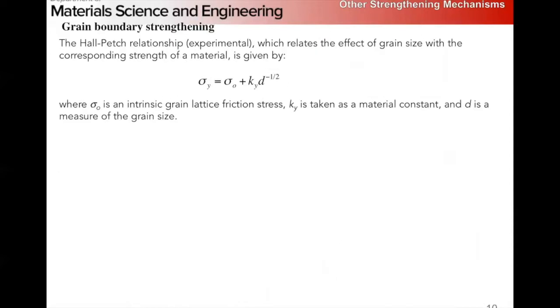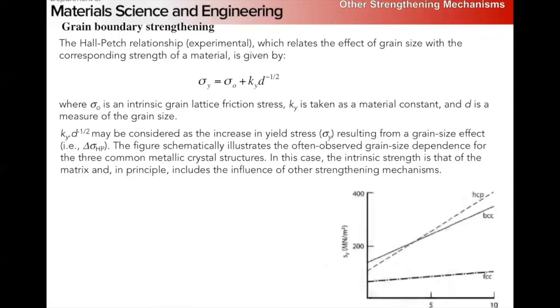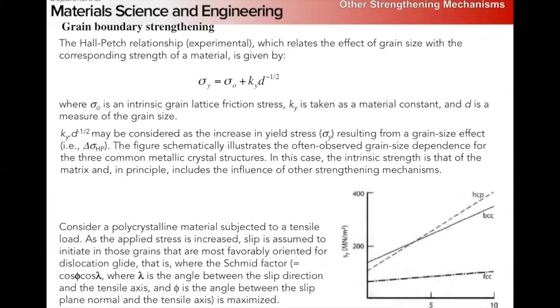Okay, so that's dipole formation. So those are two important dislocation interactions that give rise to work hardening, right? Remember that dislocations are obstacles to other dislocations, and we need to consider the specific mechanisms of interaction. And when we talked about work hardening, I didn't point out these specific mechanisms, because I thought you would be intimately familiar with them.